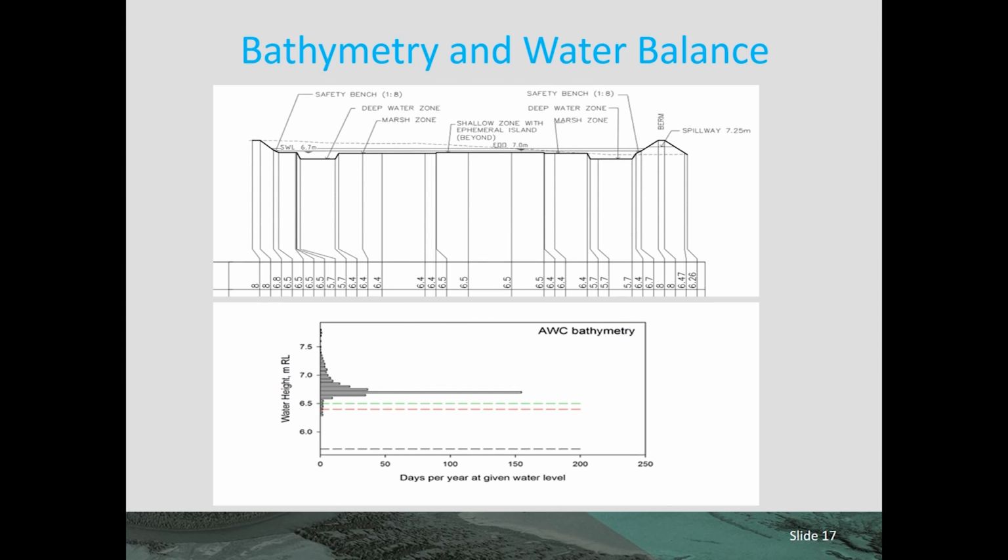Let's run some water through it and see what the height regime is. This is a different way of displaying the same data that Peter displayed earlier. I do it in days per year at a given water level. My brain works a bit better that way. You can see that if this is our design water depth, this particular bathymetry design is just not going to work. It's too deep for too long. So we muck around with our inlet and outlet structures until we get that right.